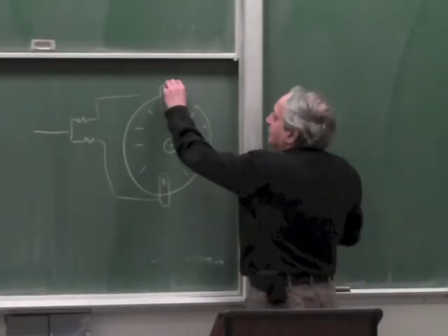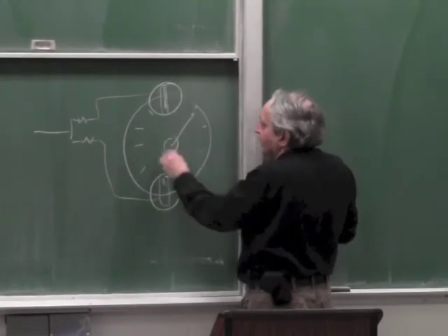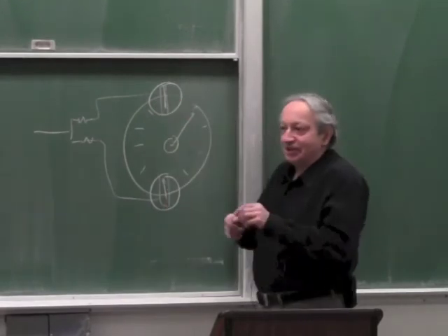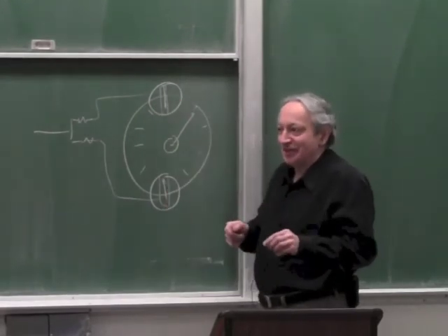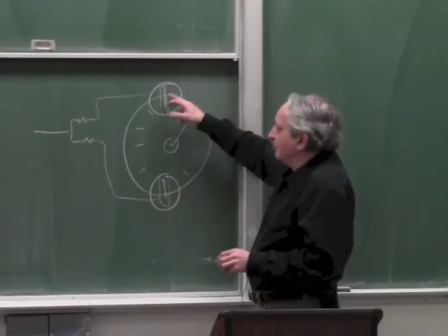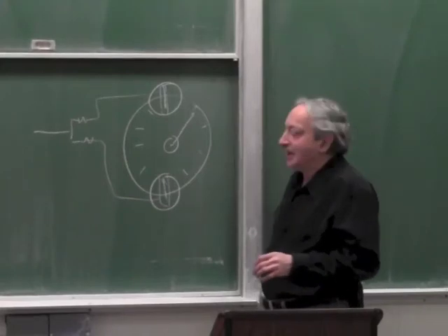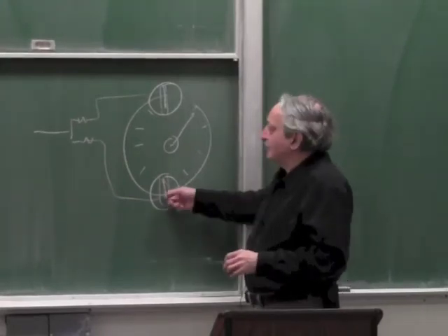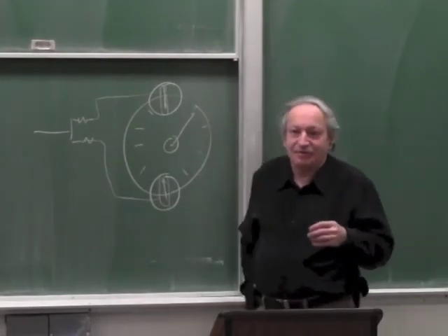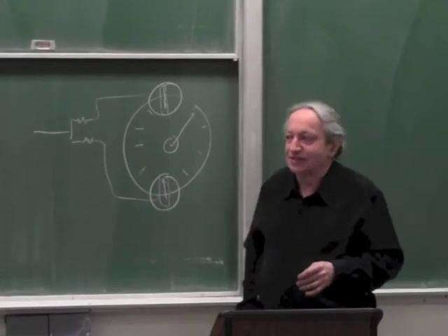It has two eyepieces, so the user actually takes a reading from here, a reading from here, and manually averages them together. Of course, in the more modern theodolites, this image was superimposed on this image, so the averaging is automatic, and the electronic theodolite is just two electronic readouts which are connected like this. But the principle of averaging to cancel the error, as you can see, is 100 years old.